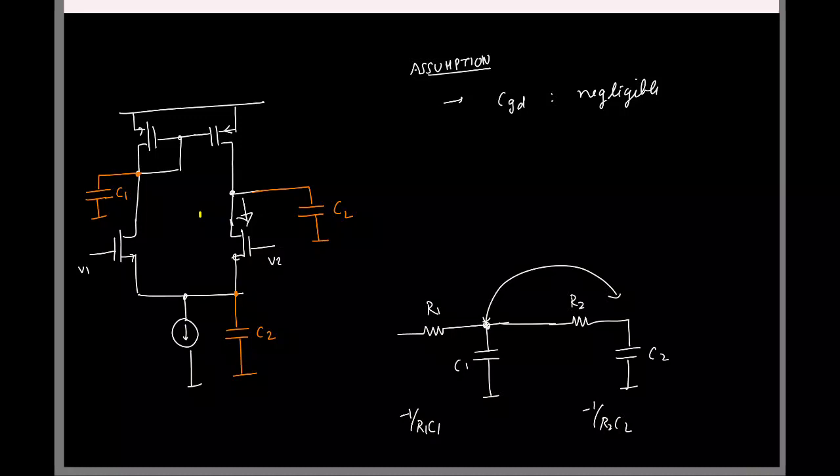The R0, right? So we'll have an R0 here. That will make sure current can flow between these two. So this will introduce coupling. We don't like coupling, so what can we do? We are in the process of making assumptions. So you'll assume that R0 for the NMOS is infinity, or it's very, very large. Okay.